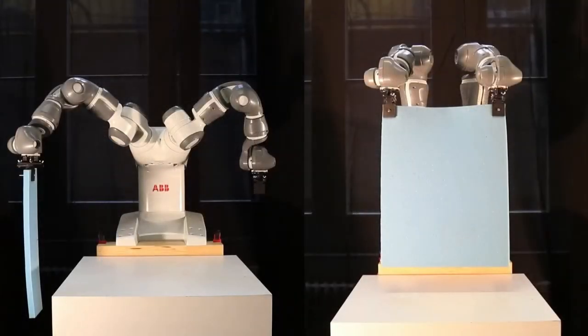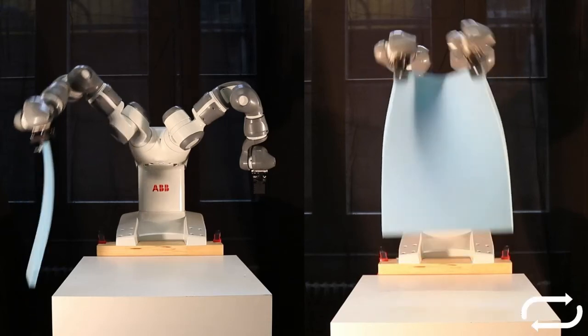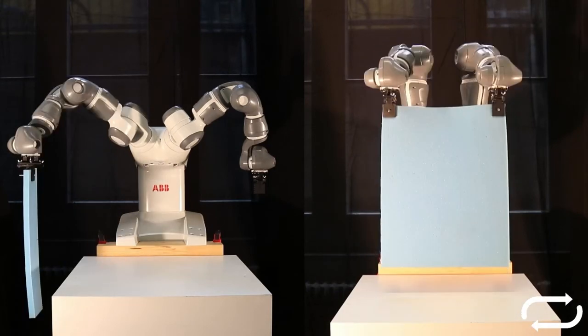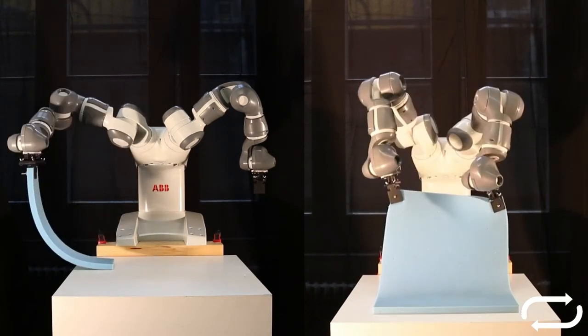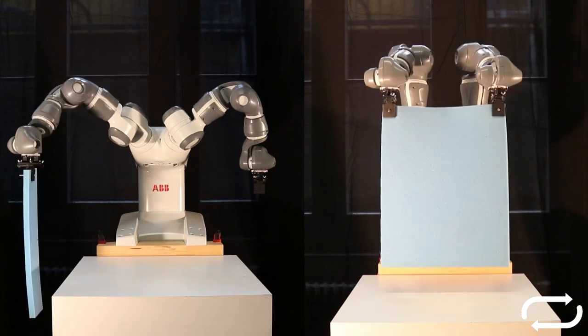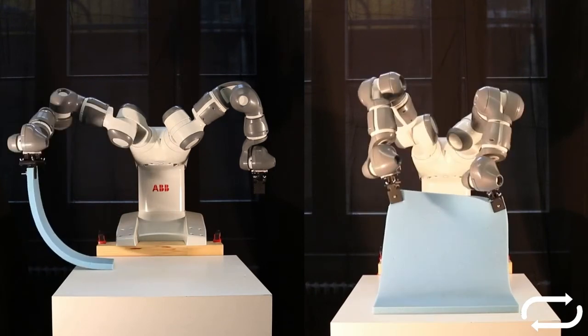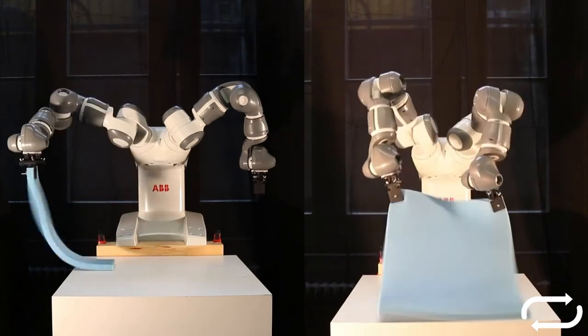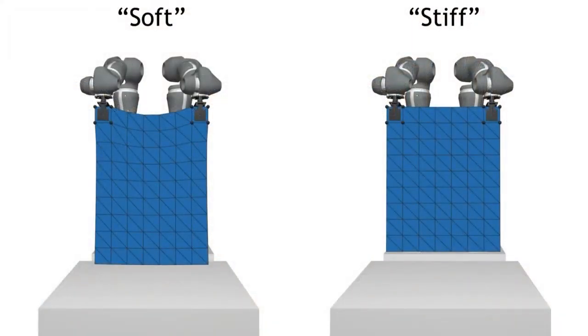We also conducted several experiments to investigate the extent to which these simulated results carry over to the real world. To this end, we sent the in-simulation computed control commands to the physical robot in an open loop manner. These two examples here show similar strategies as seen in the simulation results before. We note that since we are using a model-based approach, our framework relies on a simulation model that accurately captures the behavior of the physical objects being manipulated.